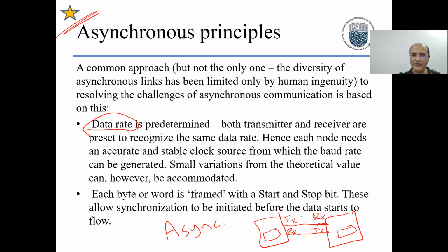And the format of the data when we send it should have a common frame, arranged in a certain way. Before you start sending a bit, then another bit, there is the duration: I send the 1, how long am I going to keep the 1 before I send the following 0? How long am I going to keep the 0 before I send the other bit?